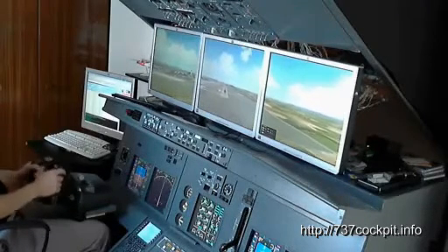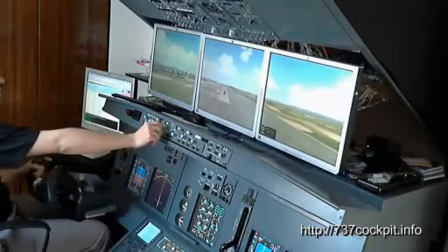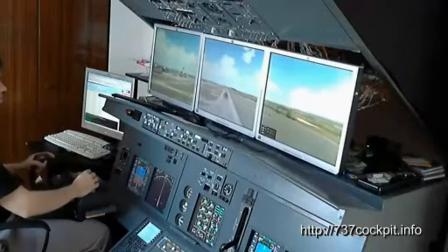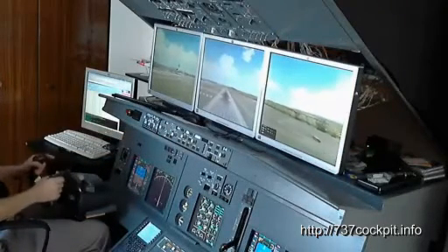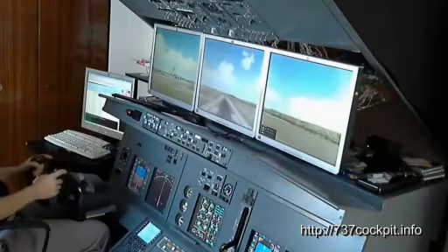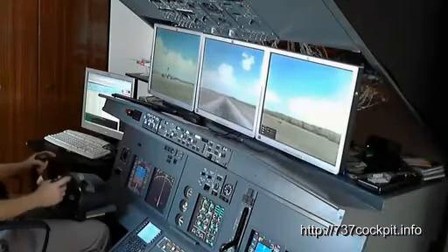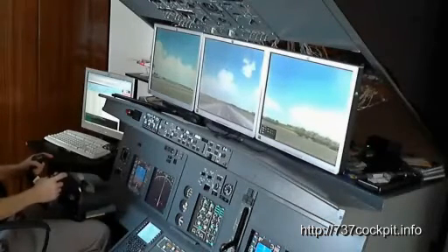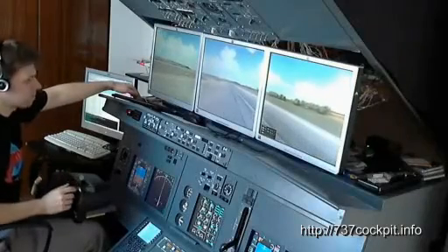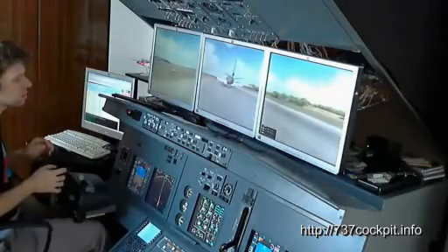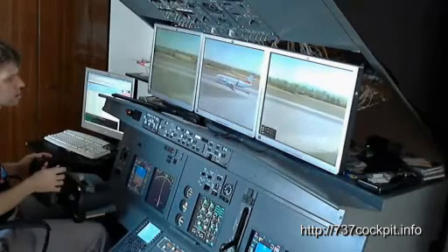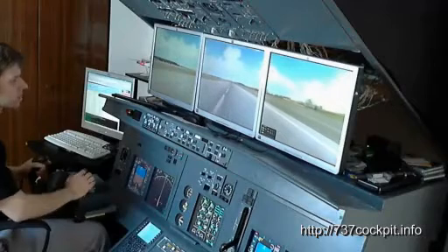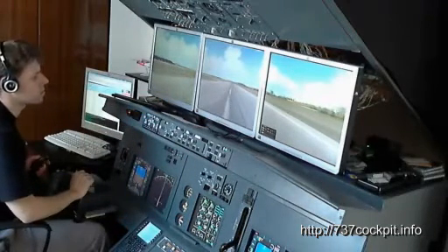Mid-market crossing, precision landing, switch the flight director off at 100. Deactivate auto throttle, pull back to idle, 30, 40, engage the flare, 20, 10. Touchdown. Set the reverse thrust. And we take exit.